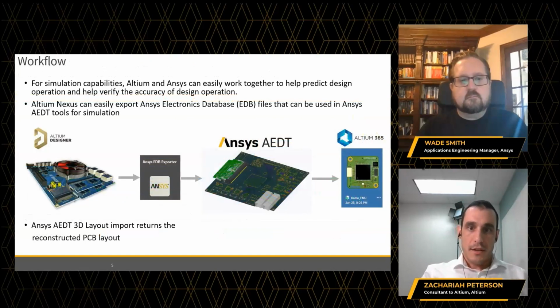Beginning with Altium Designer, the overall workflow is enabled through an extension that is included free in Altium Designer. This is a little known extension, but it's definitely key to ensuring that you can run this full suite of Ansys simulations for a product that you create in Altium Designer. So the two can easily work together through this EDB exporter simulation extension, and this is where you can export a database file that you can then use within Ansys tools to run some of the standard simulations with Ansys. This is also enabled through the Altium 365 platform.